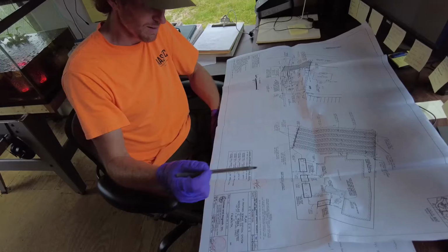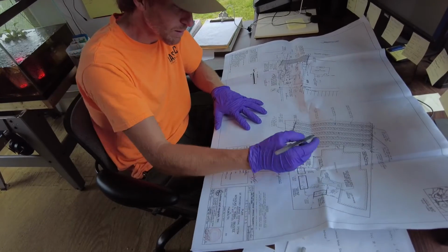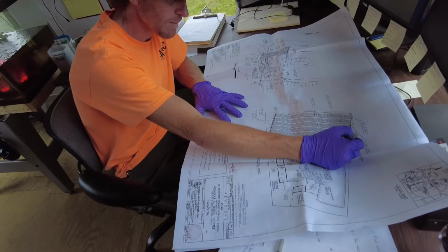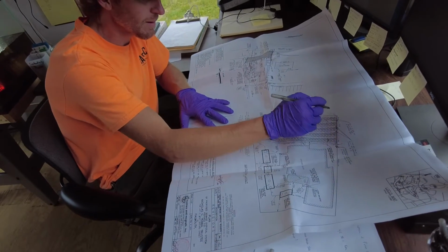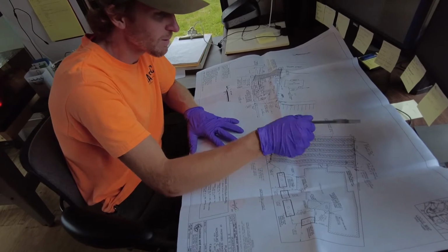So where do we begin as far as starting the process? Well, to do good maintenance, you need a good sample. You need the good information. You need to find out what's going on. So it really begins on the designer's table. The designer has to put a good sampling port in that gets a good representative sample and doesn't skew the results so that you're not operating blind.